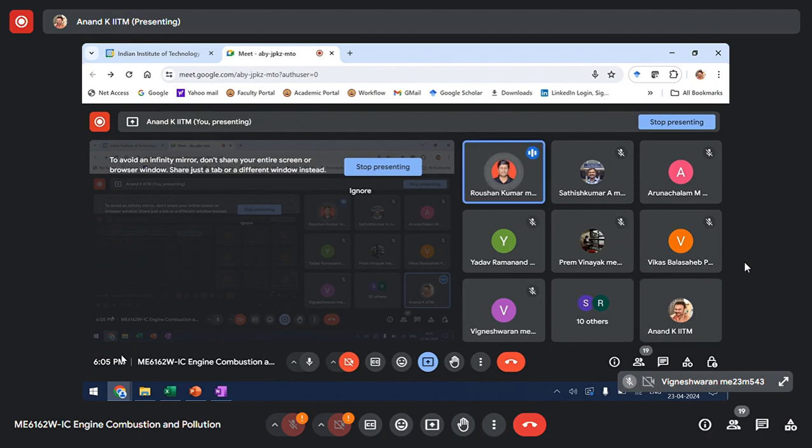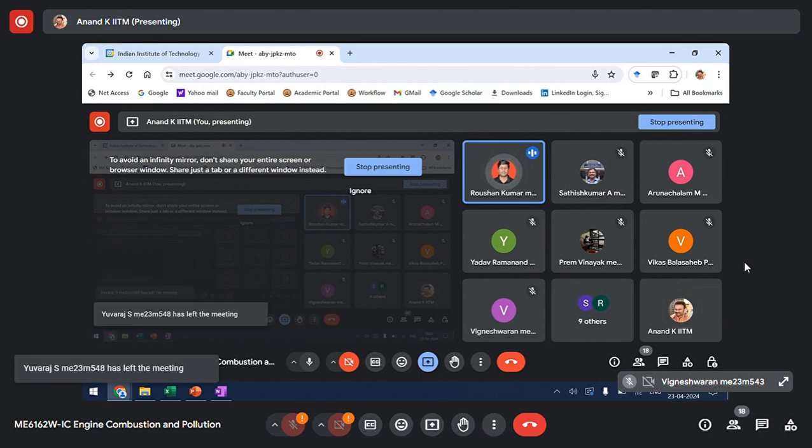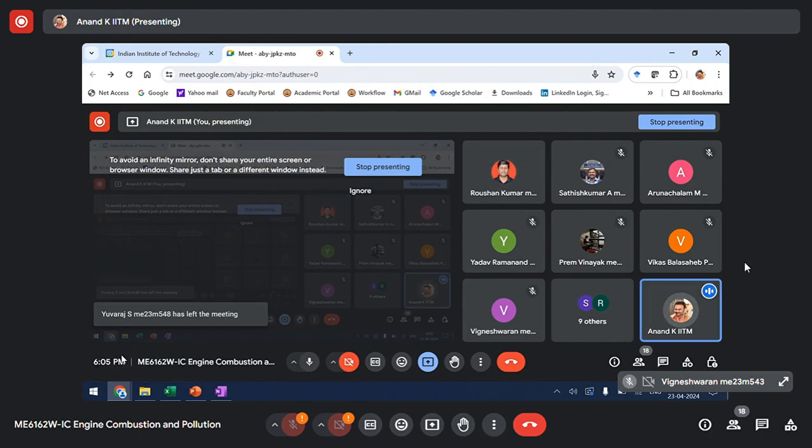So suppose, sir, if I'm making an engine of 500 cc, one is an SI engine, one is a CI engine. Typically, what will be the total value of NOx in SI and CI? Just an approximation. Irrespective of the engine type, the split is the same. If it is SI, it will be 97% NO, less than 3% NO2. For CI, based on the operating condition, it will slightly change. That is, NO will be 70% to 90%, and 10 to 30% will be NO2.